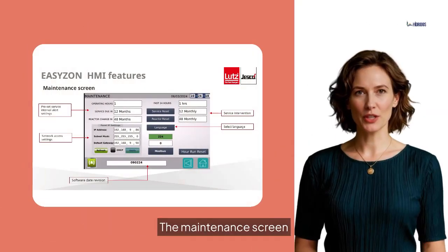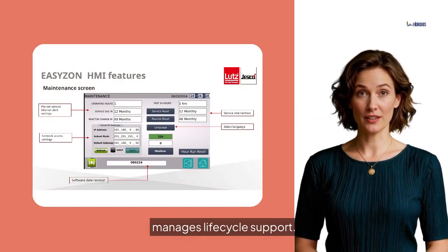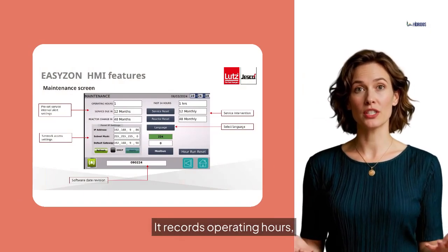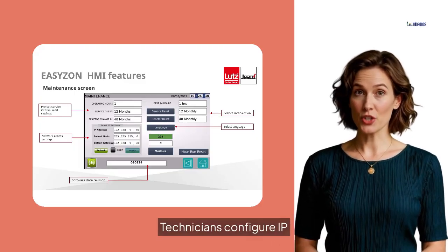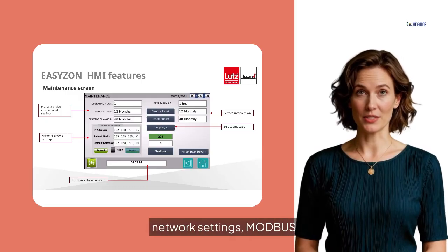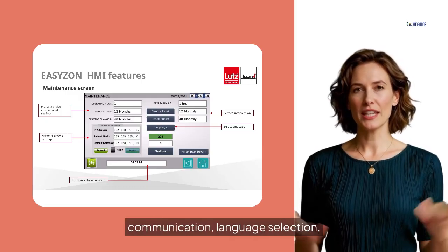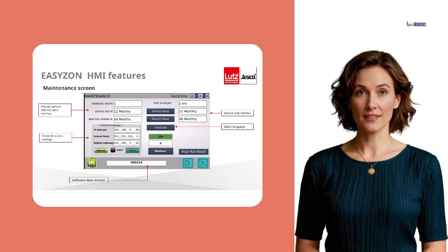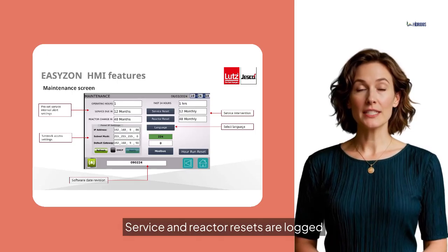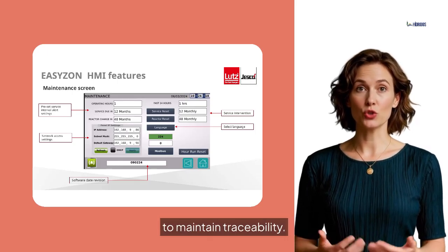The maintenance screen manages lifecycle support. It records operating hours, service due dates, and reactor change intervals. Technicians configure IP network settings, Modbus communication, language selection, and software revision. Service and reactor resets are logged to maintain traceability.